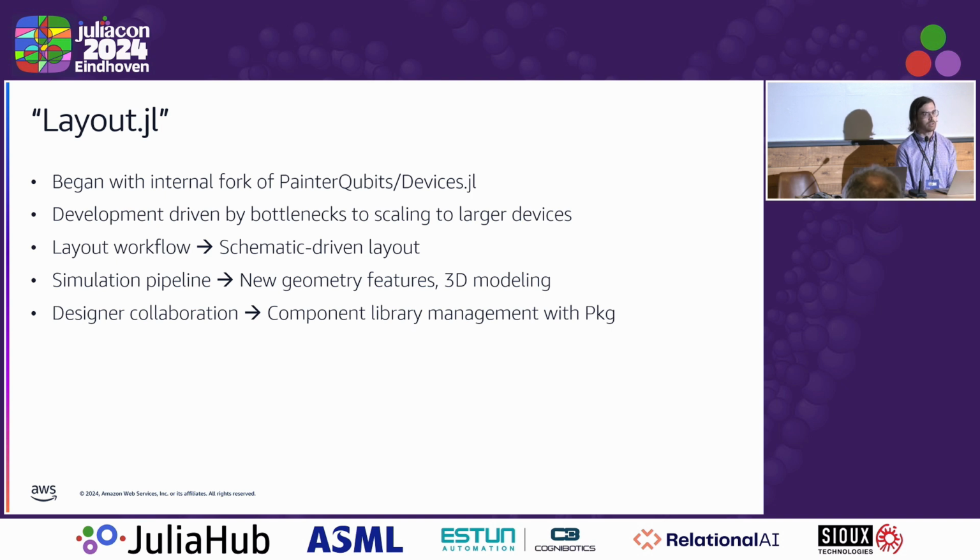As our team grows and we're building more on our own past work, we've built tooling to leverage the Julia package manager as much as possible. So a device design is a Julia project, fully reproducible. We manage a library of components in a private registry, our process development kit, or PDK.